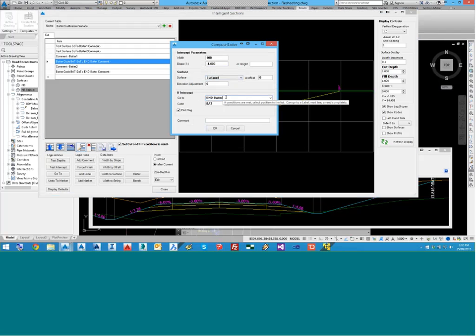The thing with intelligent sections is potentially you could say, well, match to this surface, but then cut a drain in. And I could set up this intelligent section to also include some sort of drain once it hits it. So I could say, look, if you intercept the surface, go to drain, and I might have a comment called drain and some legs that form sections that form a drain. The code that is included is BAT, so same as the batter codes we have at the moment.